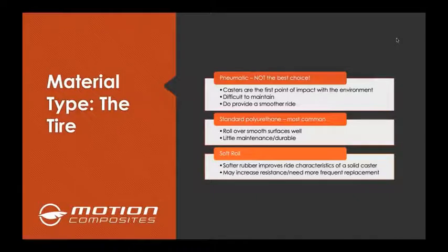There were a few casters out a little while ago. I think some companies still use them. They're a very flat profile tire, and you've got a lot of contact with the ground on a very soft, rubbery material. And when you go to initiate a turn with those casters, it's much harder to initiate a turn because the caster has so much surface area on the ground that it bites much harder, and it feels like it's resisting you a little bit when you go to turn from a dead stop. So it all kind of plays into that on a caster choice.